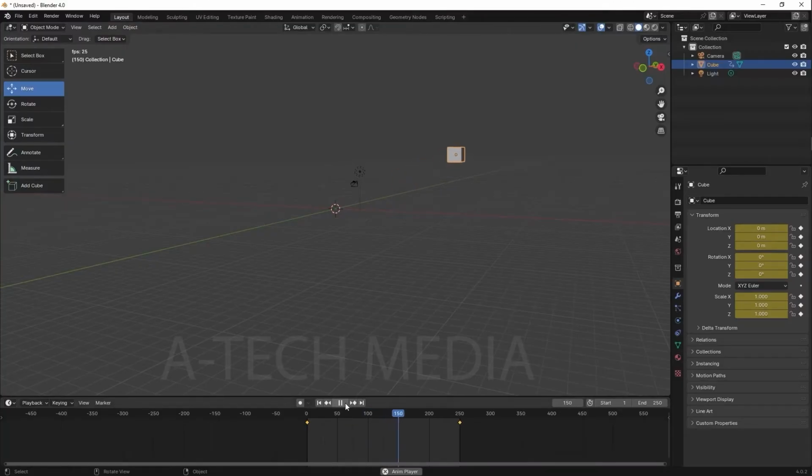So right now, I want you to take note of this process. First, you insert a keyframe, your start keyframe. You insert the end keyframe. To animate an object, you have to insert a start keyframe, which is a record of the properties of the object before the change will start, and then I insert an end keyframe, which is a record of the properties of the object after it has changed.